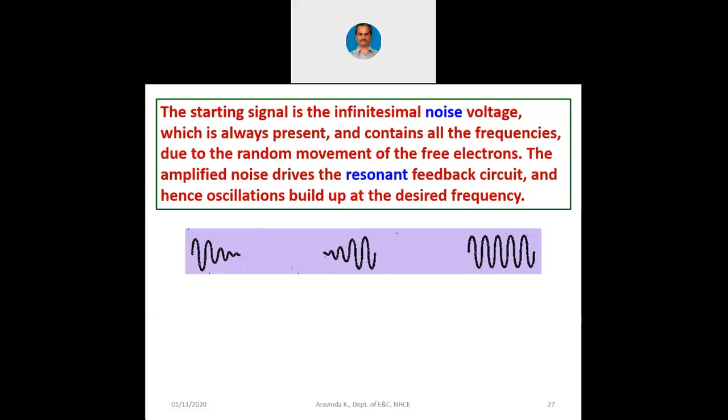It means after the circuit reaches a particular amplitude of these oscillations, there will not be any further increase. Again, that depends on that particular factor A beta. Even though A beta is 1, oscillation will not increase further, and that A beta itself is causing it that way. Let us see that later on anyhow.